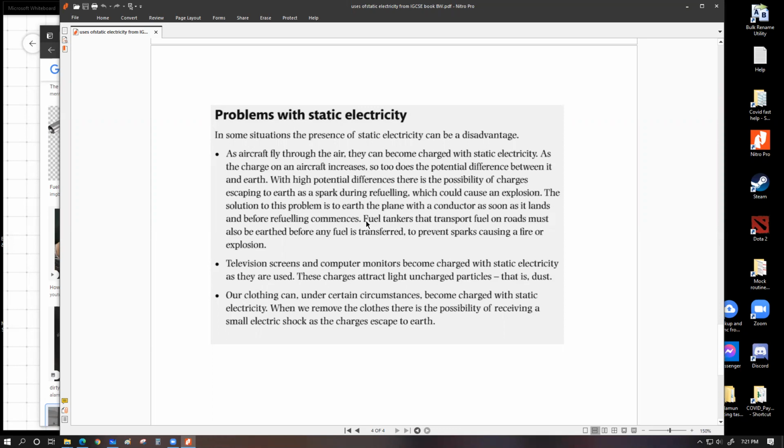So I'm starting again. If the aeroplane slash vehicle is not discharged before refueling, it is possible that when two oppositely charged bodies are brought closer, there will be a spark, comma, which might ignite the fuel and air mixture. Fuel itself cannot burn. You need to have air present as well. Whenever fuel and air get mixed together, that's basically what is explosive. Fuel itself without the presence of oxygen, not explosive. Oxygen itself without the presence of fuel, not explosive. Combination, explosive. So a spark can ignite the air fuel mixture,